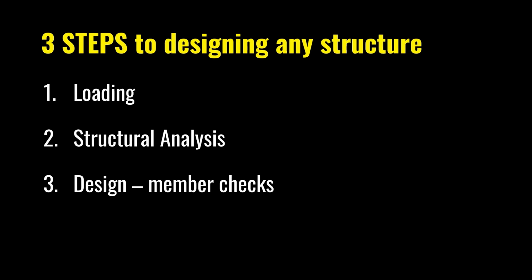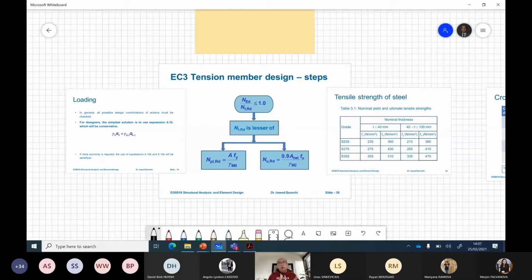The purpose of design of structural components is that we always compare applied versus resistance, or in some countries demand versus capacity of the section. Demand over capacity is termed utilization. If demand over capacity is 0.5, then we can say that 50% of the capacity is being utilized. That is termed the utilization ratio. And in all designs, pretty much, we will be doing this kind of exercise.